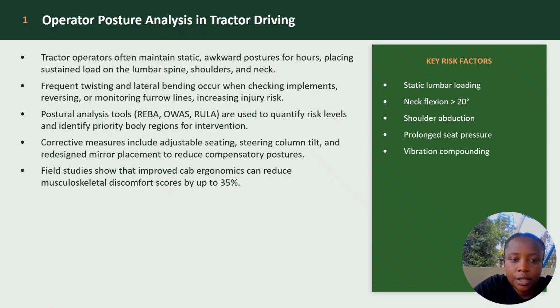The fourth one is that corrective measures include adjustable seating, steering column tilt, and redesigned mirror placement to reduce compensatory postures. Field studies show that improved cab ergonomics can reduce musculoskeletal discomfort scores by up to 35%.